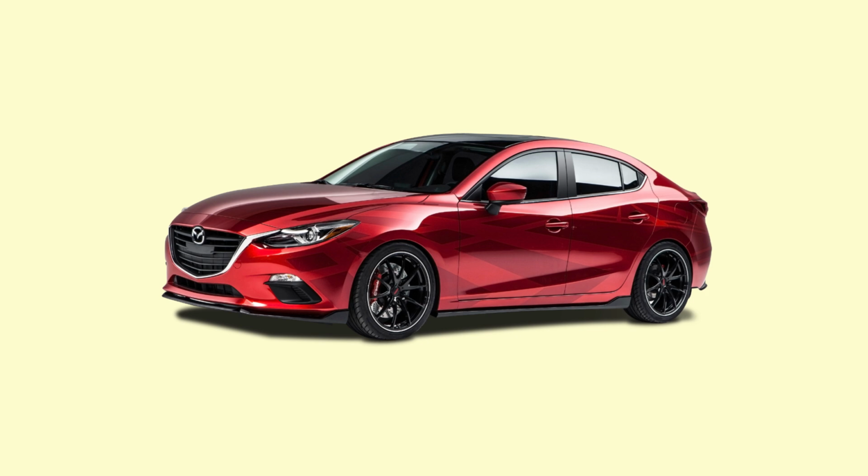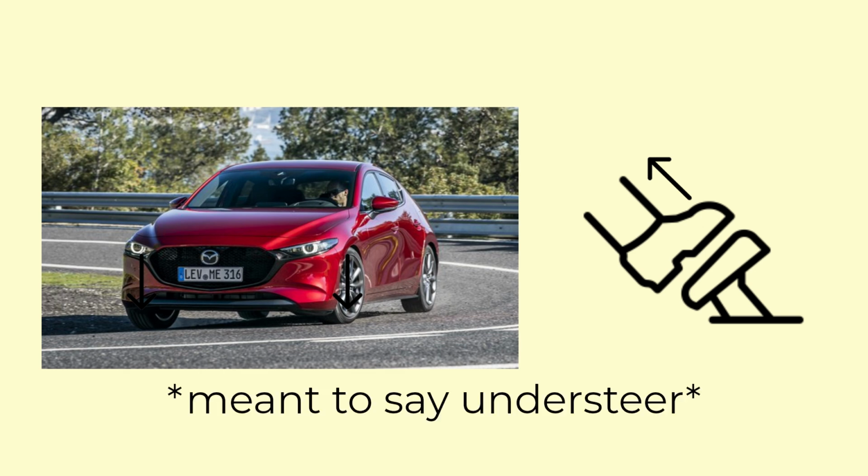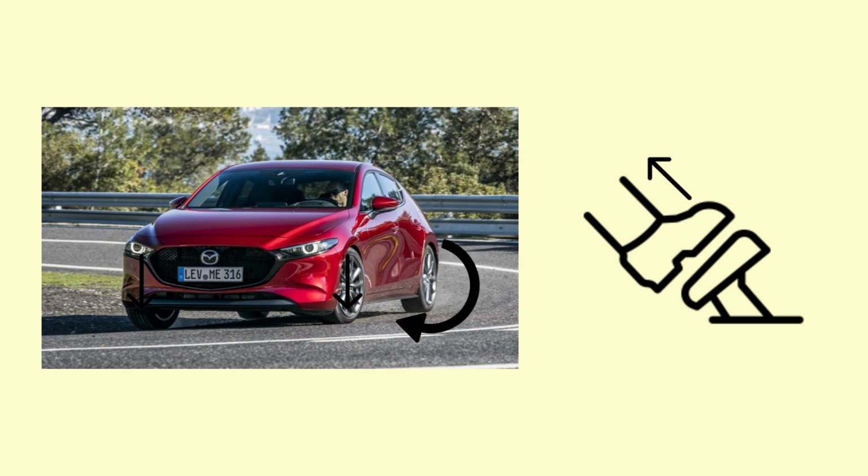Now that we understand why FF cars tend to understeer, let's introduce some driving techniques to help manage it. One of the simplest methods to reduce understeer is a technique known as lift-off oversteer. When you lift off the throttle mid-corner, a braking force is created that shifts weight back onto the front tyres, where the car's opposite reaction to the lift-off is that suspension leaning forward, shifting the weight back to the front tyre. This increases the grip on the front tyres, reduces understeer, and in some cases, even causes the rear of the car to rotate more, leading to oversteer.